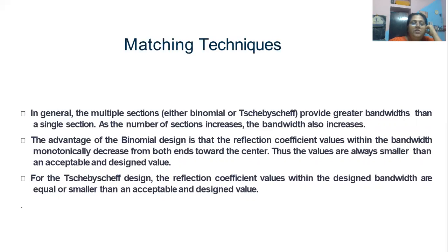Now, the advantage of the binomial design is that the reflection coefficient values within the bandwidth monotonically decrease from both ends towards the center, and thus the values are always smaller than the acceptable design value.